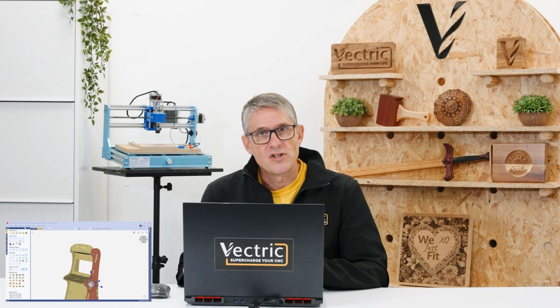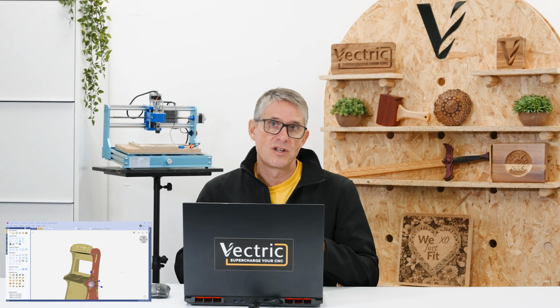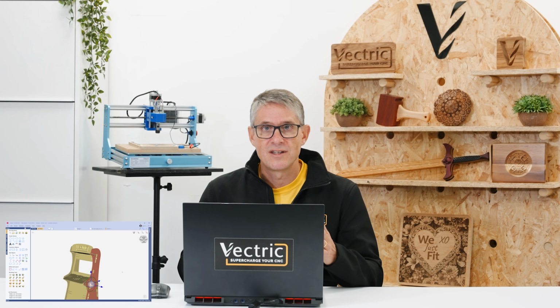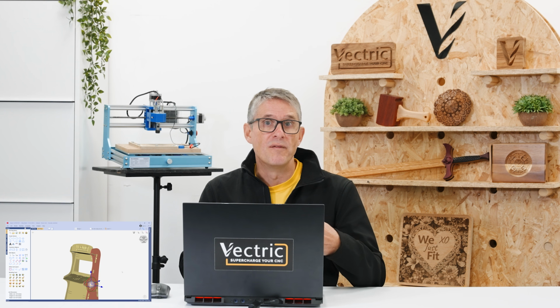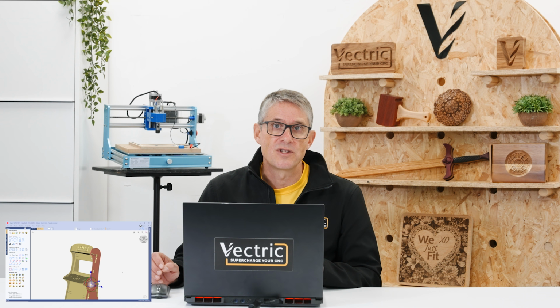So this also opens up another interesting thing which I think is very valuable, which is when you're working with a real object. For example, the other day I was constructing an enclosure that needed to have a Raspberry Pi touchscreen in it, and the Raspberry Pi touchscreen is obviously a purchased component. It has fixed dimensions, and I wanted to ensure that when I assembled the rest of my enclosure from plywood, the Raspberry Pi screen would fit. So another thing you can do is build a quick mock-up of a real world object that you want to check for scale and fit against your internal designs. So I think this is going to be a really valuable and important part of the process from next year.